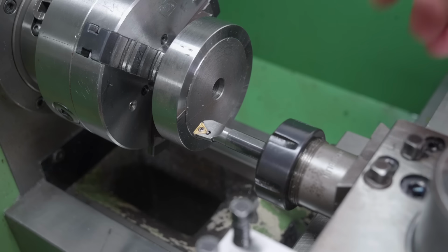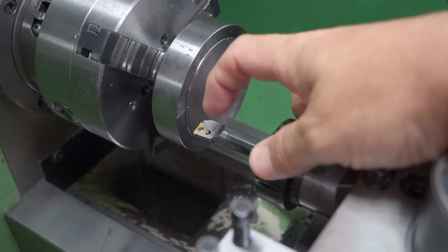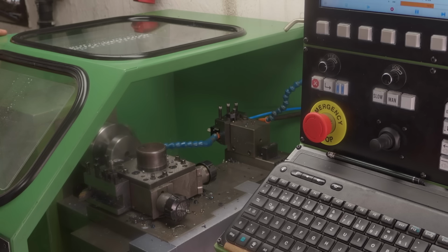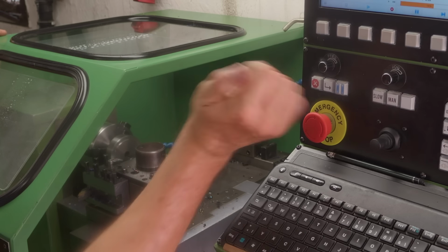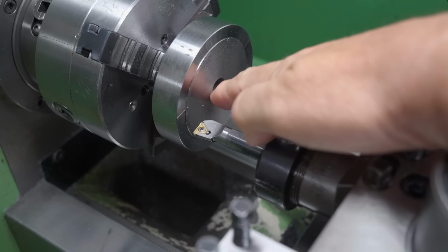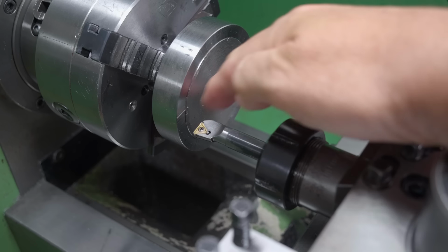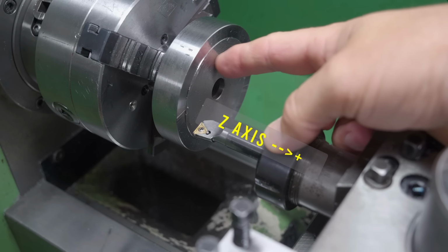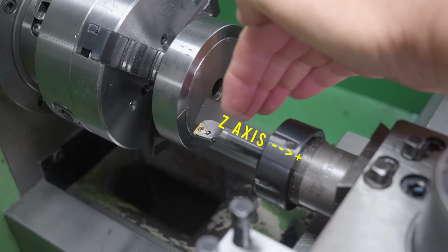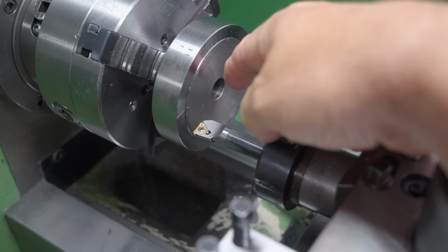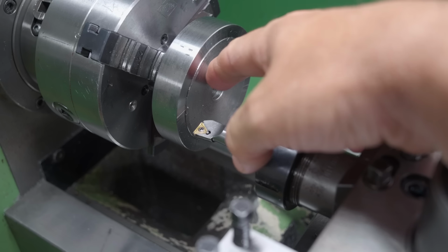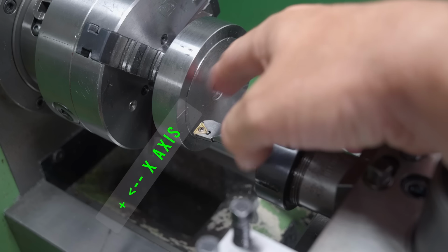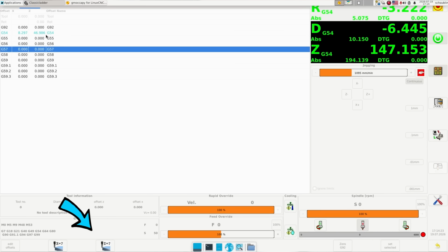Now, when I left you last week, I just managed to drive this boring bar into this piece of metal out here and install the spindle. It was supposed to be boring, of course, in the middle, but I'd made some sort of an offset screw up. I think I'd reset the Z offset position, like where this is, but I must have entered the value in the X offset, radius to diameter line. At least that's what I'm assuming I did wrong.